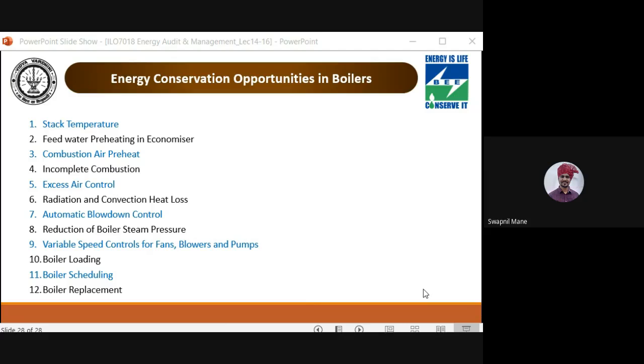So blowdown is of two types. Okay, we have the manual blowdown and automatic blowdown. Manual blowdown we also call a periodic blowdown. So periodic blowdown means what? After some intervals, I know that my water will lose its tendency, and all the minerals that are suspended in the water will get deposited after some usage of the boiler. So I will carry out the manual blowdown, or plant blowdown.